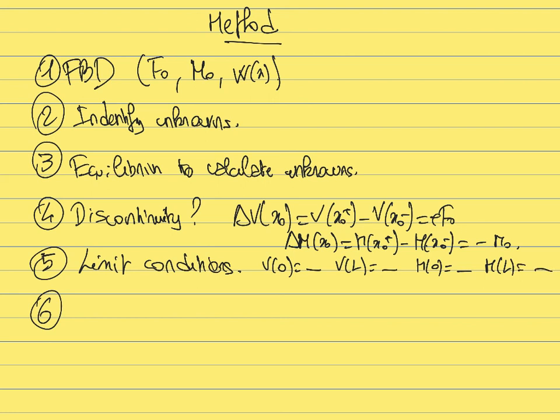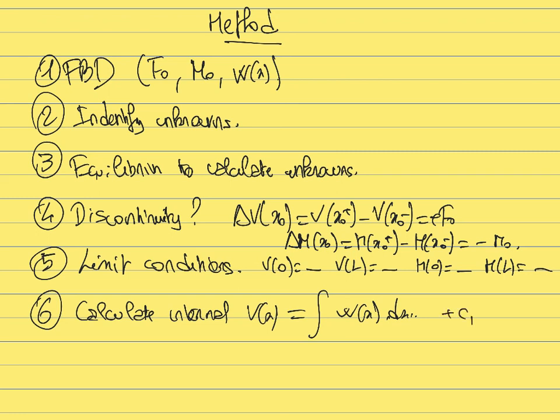Once you have this, you will now calculate the internal shear V as the integral of the distributed load. You will take the distributed load and integrate it to find the shear. That is going to give you one integration constant.